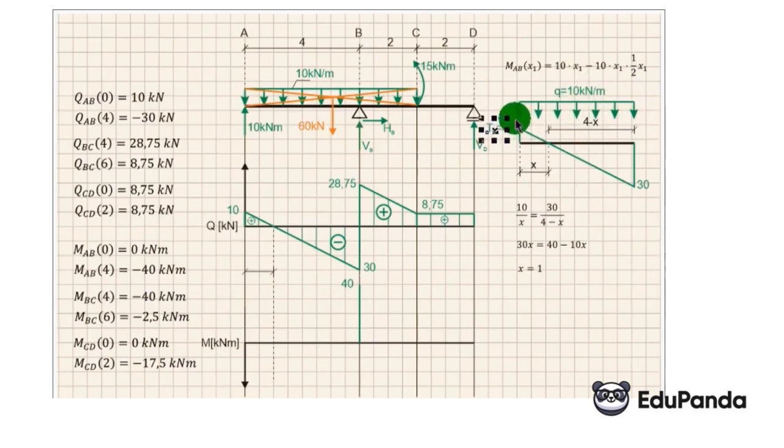So if we denote the value of the continuous load as q, then the first value on the shear force graph as TP, we can always denote that x0 will be that first value from the shear force graph divided by q. Here we have such trivial values that this is not the best example to present it to you, but that's just how it turned out. So as I said, both methods will work for any case.